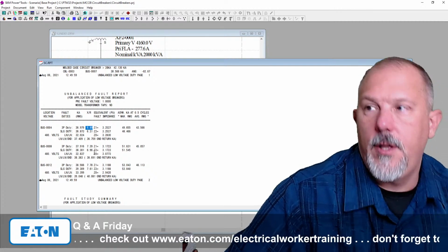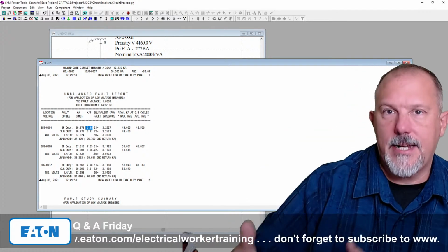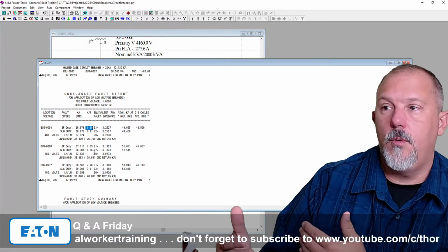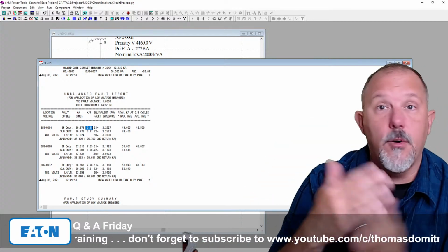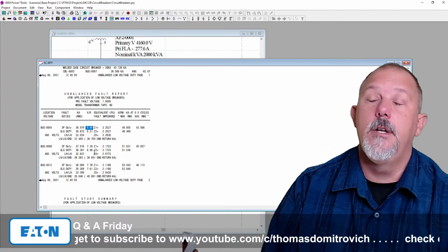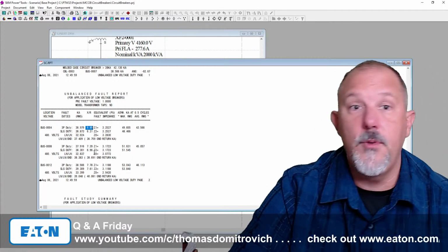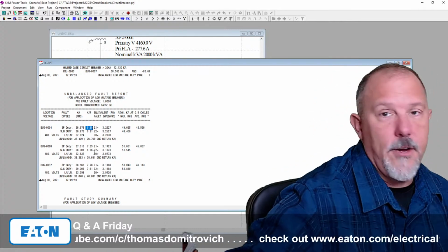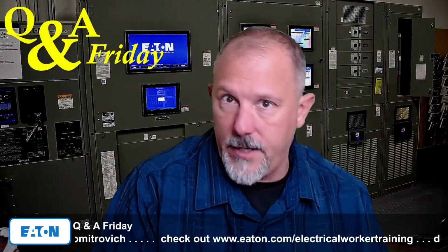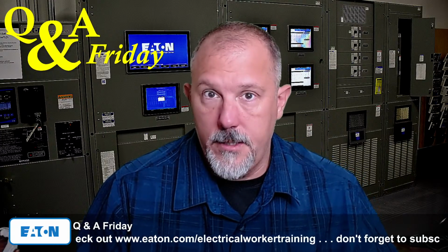So the more conductor you add on the secondary of a transformer will bring down your X to R ratio. And why? Because there's a lot of resistance inside of a conductor. So my answer to you, JW, is that in real life, where you might see a concern would be on the secondary of a transformer with a short conductor run.